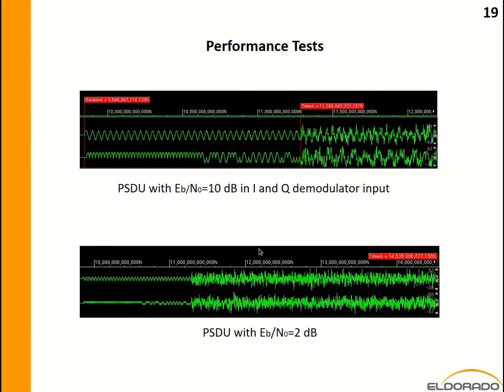To run performance tests, we created direct tests to set frequency, operation mode, and modulation scheme, keeping the randomization just for PSDU data and the AWGN seed. The noise is placed only in the PSDU. Then, the MATLAB script analyzes the maximum absolute value of the peak in the real and imaginary parts of the signal and divides all samples by this value, making it possible to send the signal without clipping the demodulator input. This process is done for each ABN0 value.